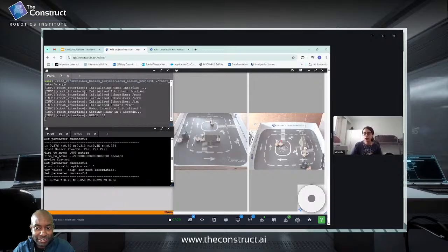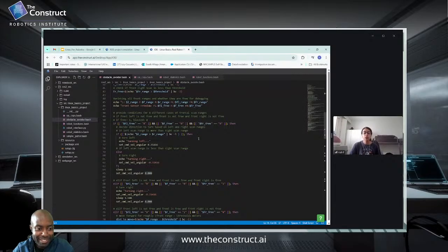And I tried to think about ways I could fix that. First I tried changing the threshold value. So I tried increasing the threshold a little bit more. I could maybe give myself a little more leeway for it to turn. I don't know what the size of the robot is. If I was there in real life, with a lot more real robot testing, I would have been able to zero in on a threshold value that's larger, but still close enough where we're not stopping half a meter from the wall.